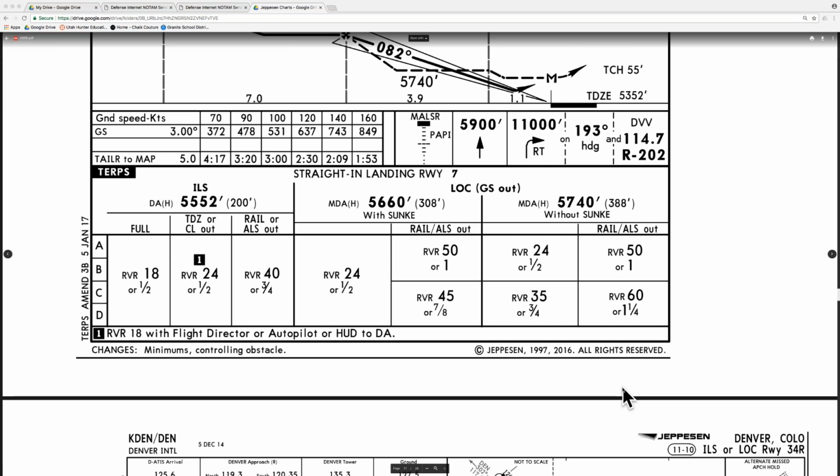Worst case scenario would be that the pilot runs out of fuel because he's waiting for alternate minimums, or the ability to land at the alternate airport. But that's why we pad our alternates, because if worse comes to worse, he's still legal to land, technically. He's just not legal to list it as an alternate.